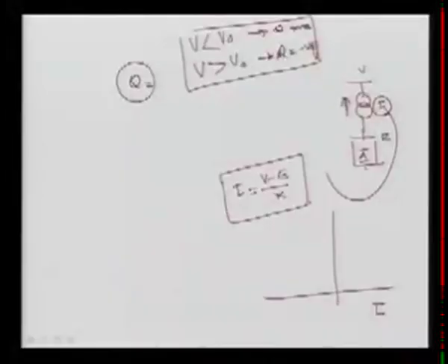Sometimes people ask why, in this VI characteristic of the STATCOM or SVC, we do not go for zero slope, and always go for some slope. It is a minimum of 2 to 5%. As I said, if it is a 0% slope, the operating point is not well defined; for the same voltage, it will be oscillating, hunting. So we intentionally go for 5%, or 2 to 5%. 0% is not desirable, however we can go for that.